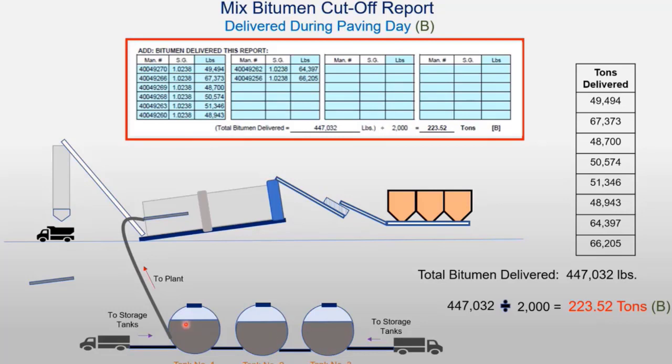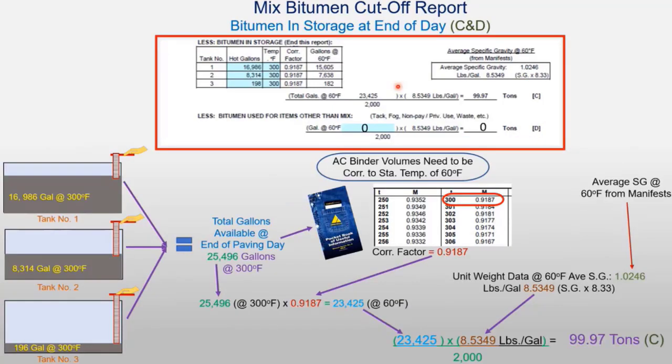And so there's things happening during the day here. There's mix adding to the tank, or transports are filling the tanks up, but it's simultaneously being drained by the plant. And so we're keeping track of that. At the end of the day, we do the same thing as we did at the beginning. We stick the tank. The contractor sticks the tanks in our presence, and we go through the same thing again. We end up with a ton number here again.